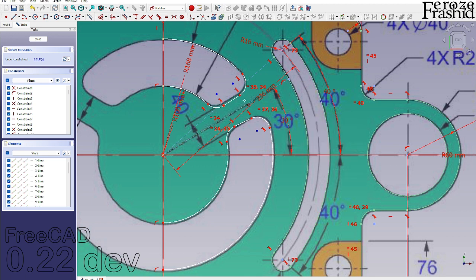We drew that because I want to say this line and this line that we just drew will be parallel. So that's P on the keyboard. Now I can say these two points are symmetric by the line we just drew, and then the distance between them is 40.